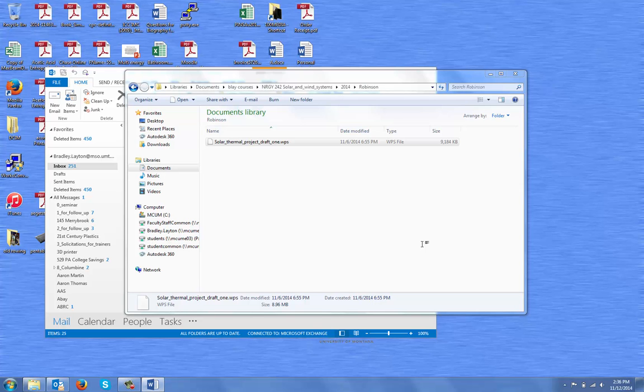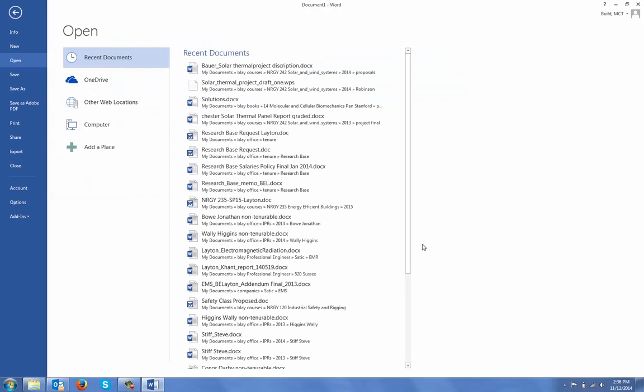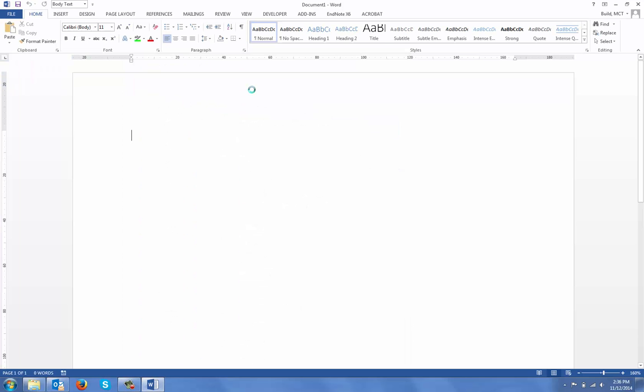We did the math on that, and that was like 4.5 kilowatt hours per day, I think. We could do an overlay of that one and her Solar Pathfinder to show that she would get less than 1 kilowatt hour per day.